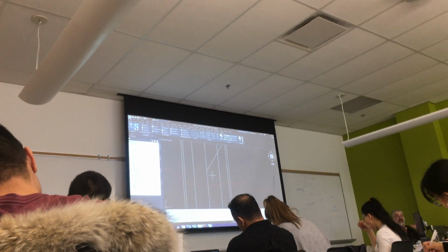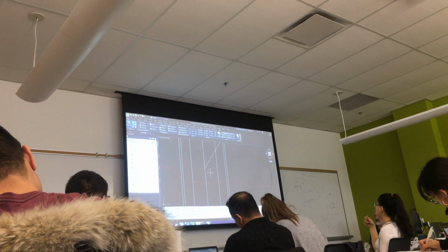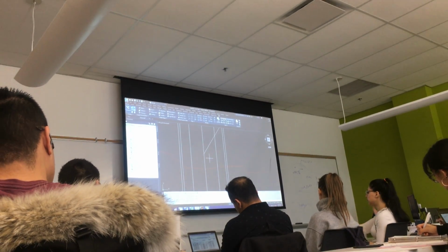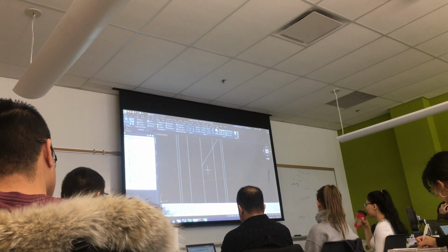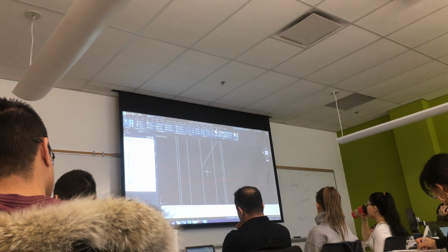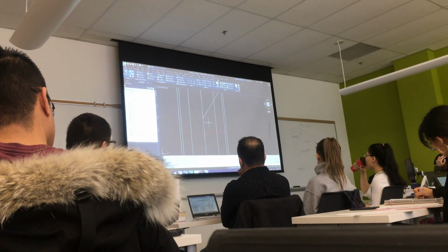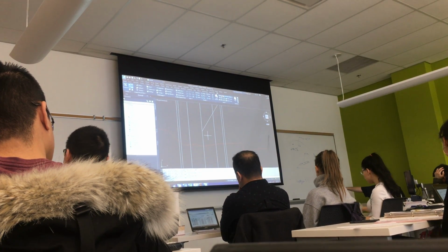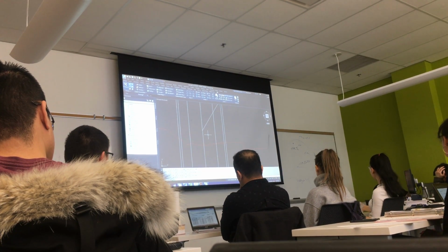Now, when you offset the rounding of 0.5 meter or 1 meter, the roundings are either 0.5 or 1. There's no other options, depending on the road classification, speed, design hour volume, so it's either one of those 2 numbers. To draw what you need to draw, you need the center of the rounding. So if the rounding is 0.5, what's the offset to the middle?